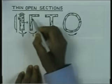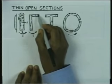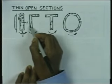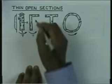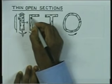And since the stress is going to remain constant at the edges, we can write the stresses in terms of the angle of twist per unit length and the thickness here. For this segment also we can write the stresses in terms of the angle of twist per unit length and the thickness here. And the torque capacity for this portion can be written in terms of angle of twist per unit length and the length of this segment and the thickness. For this portion also we can write in a similar fashion.